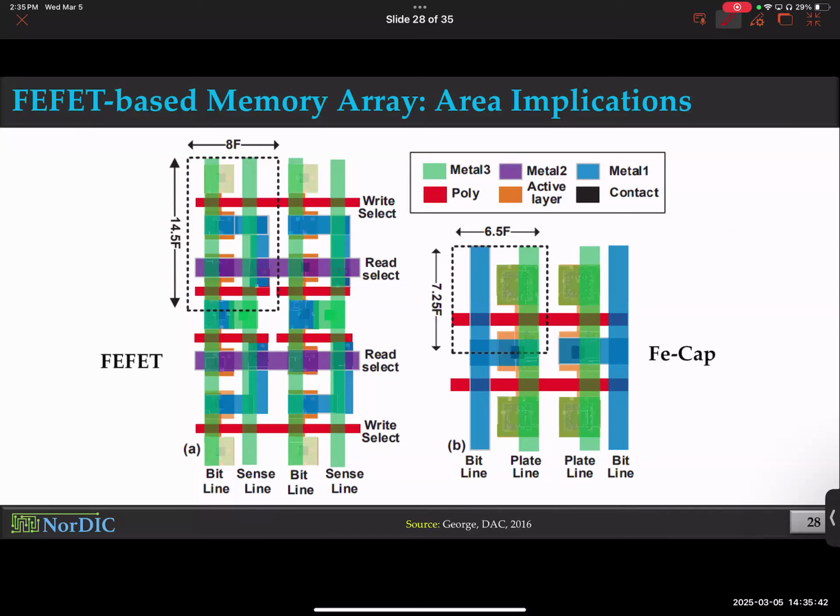Okay, and by the way, this is one cell. This is the other cell. This is the other cell. So that's the beauty of memory design. Once you design one cell really well, like literally this one, just copy, paste to the right, row, column, row, and column. You see that? You don't even copy paste anymore. There is code that you write, like, okay, repeat it 256 times across the row. Just put the number 256, and it'll make it, right? I teach it in 651. I don't know if you have taken ECE 651. Typically, Professor Rose and I used to rotate on this course.